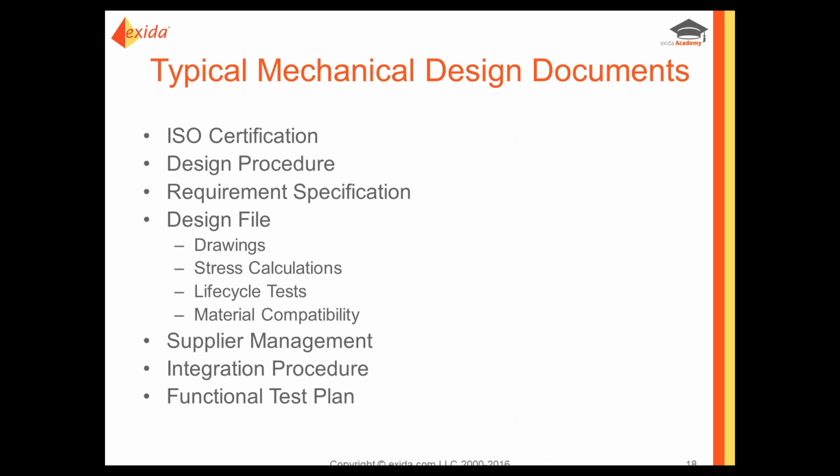While a semi-formal approach, good experience, or a reputable valve integrator may or may not be okay for general process requirements, which is for the ultimate user to decide, it doesn't meet the rigor and traceability that 61508 requires. And that's very hard. Once you get those valves in the plant, it's very hard to go back and generate or collect that evidence.